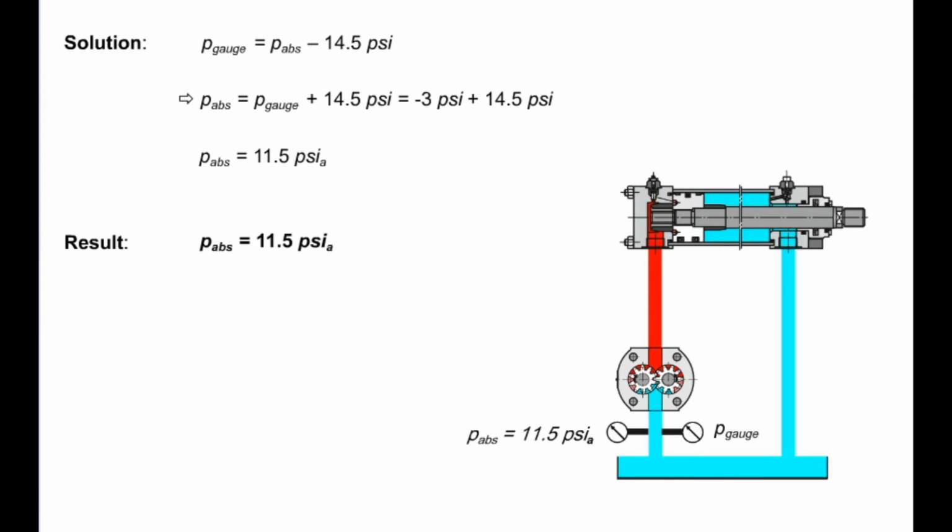In those cases where the pump inlet is located above the level of the fluid, attention must be paid to the value of pressure prevailing at the pump inlet. This pressure should not be too low, in order to avoid such negative effects as cavitation.